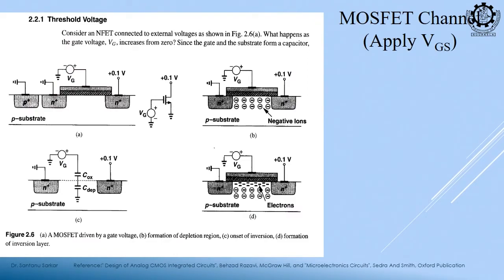So, if we discuss how this MOSFET is working, at the start, suppose there is no gate voltage, VGS is less than how much? VTH, this is the threshold voltage. Then what is the condition? MOSFET is in cutoff. Drain current is equal to source current is equal to 0. We know three regions, right? The current characteristics are similar to BJT.